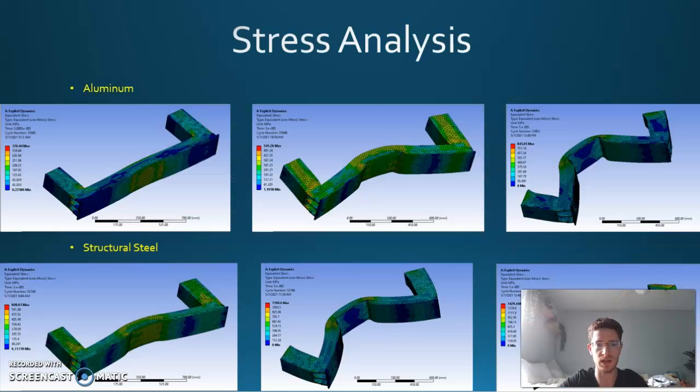The interesting thing is that, I'm not sure if you're able to see here, but the maximum stress in all situations was usually located on these corners right here instead of on the rest of the model, which was something I thought was quite interesting. And it was usually lower wherever the contact area between the bar and the block was, which basically didn't deform, it just almost stayed flat, and the other areas were the ones that deformed more and had more stress on them.